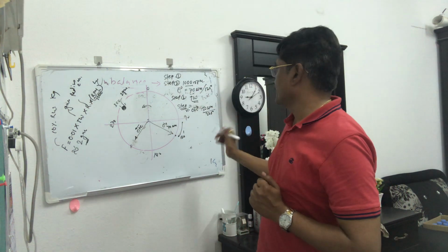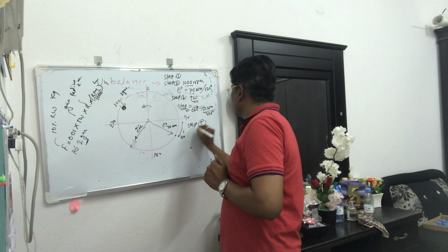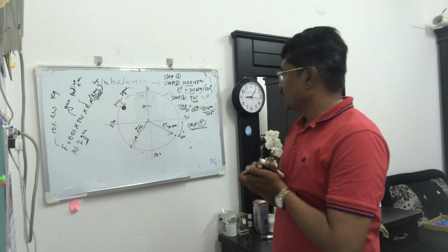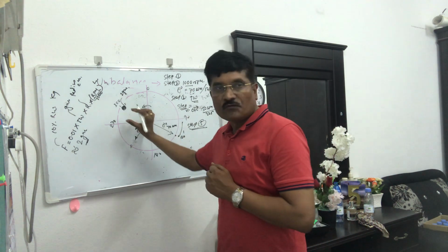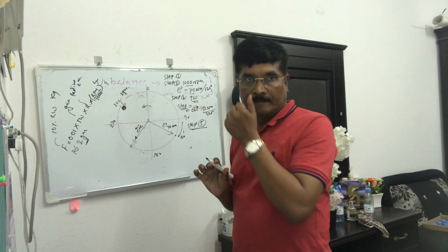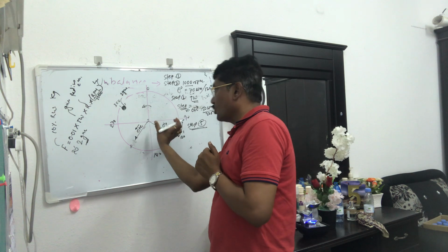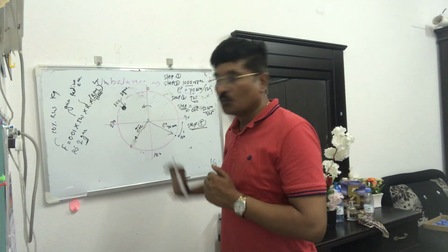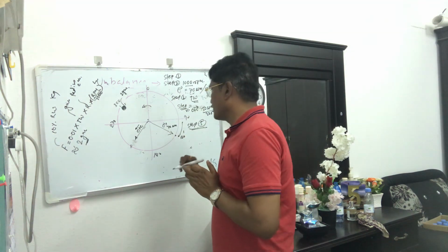Now the magic starts. Now we will go for step 5. What do we have to do? We have to find out the effect of only the trial weight. For that we have to subtract the O vector from this O plus C vector. It is not a big calculation.